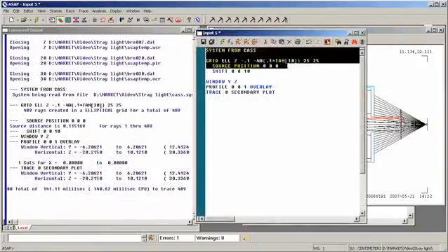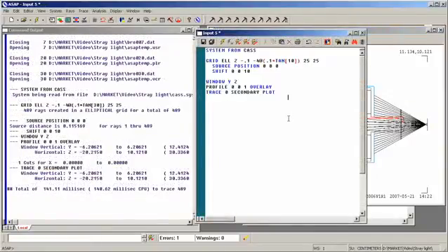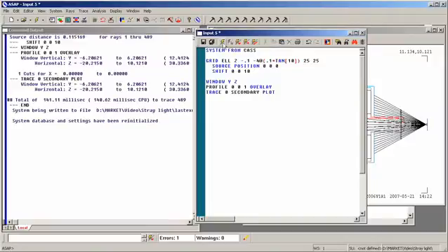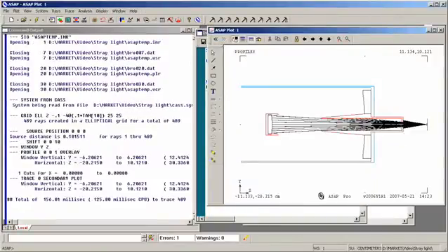We now have before us our file that we're going to be using to do our backward ray trace. The file starts at the origin and then propagates from there to the secondary mirror and then stops. Let's do an N command and go ahead and run this file. Okay, so here are our rays propagating backwards from the detector to the secondary mirror and stopping. They're actually reflecting from the mirror, but they are not propagating any further because we've told ASAP to stop there.